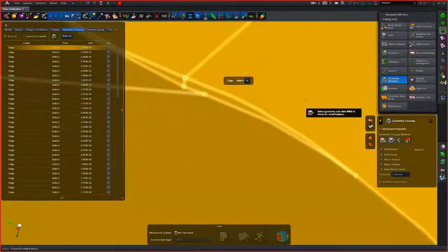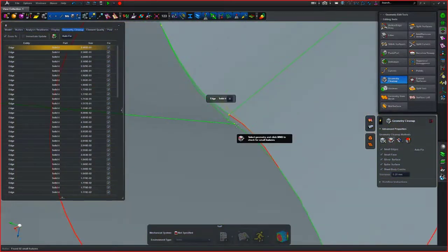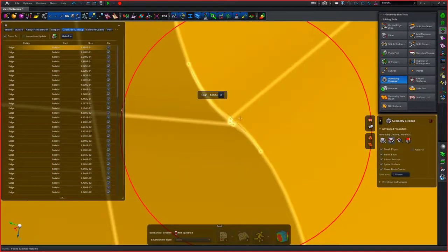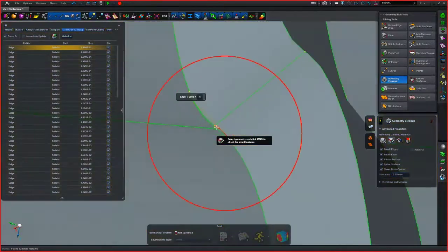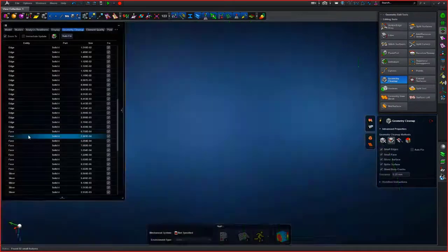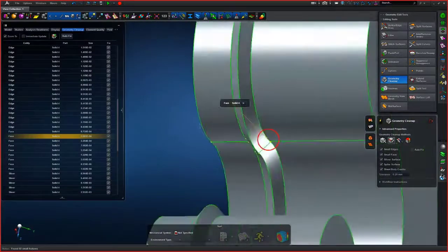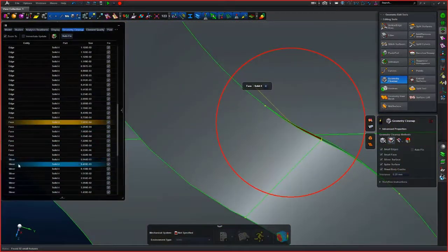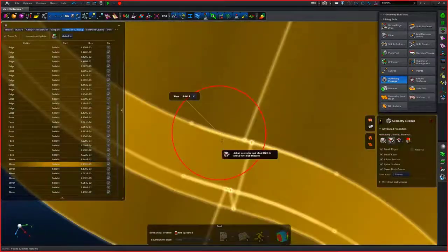And I hope you can clearly see this. There is indeed a small feature that came through from the CAD product, and that is the reason why the defeaturing didn't work, because I didn't include those small faces. If I go down the list, I'll see there's a list of faces as well that falls into the small category, the same ones. And there are also some sliver elements, essentially the same ones as well.